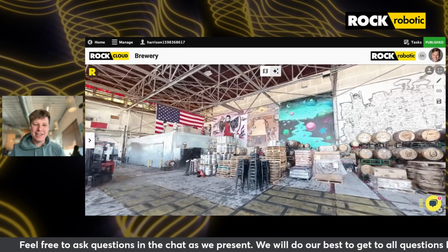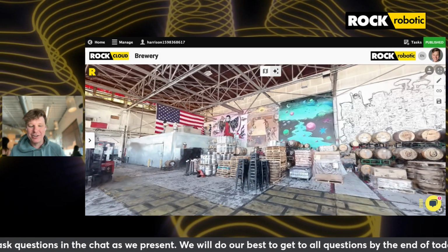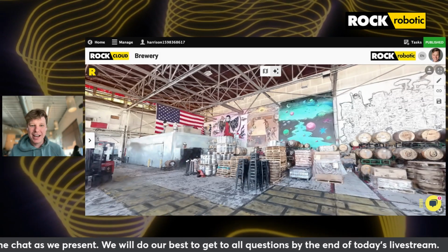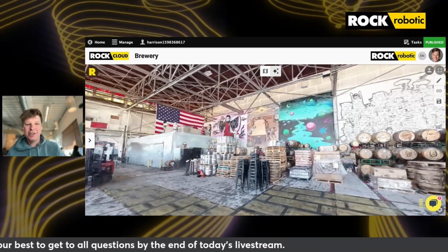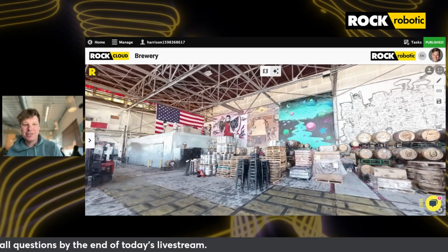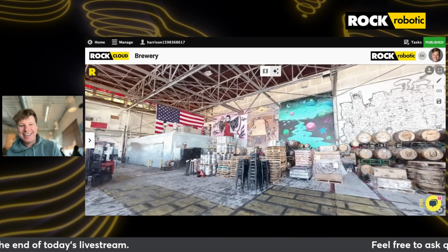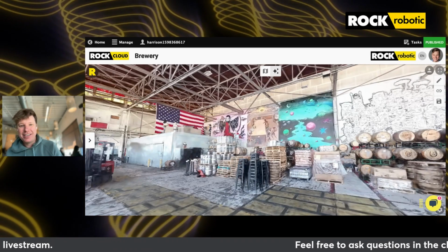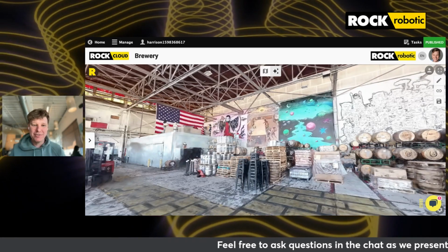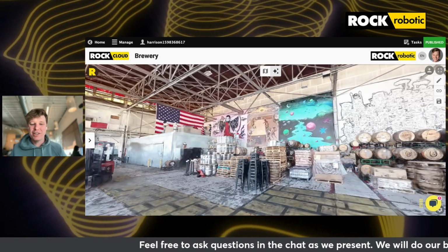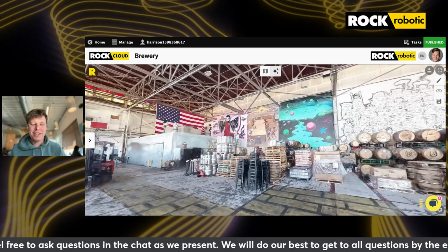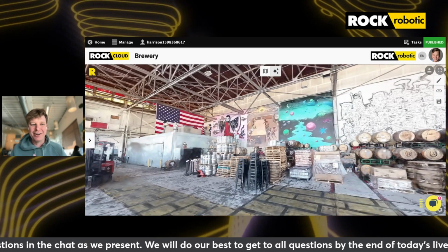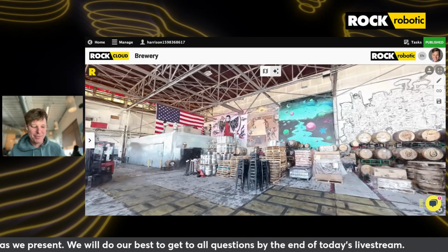And you're going to get that highly accurate, about 2 centimeters accurate at a recommended AGL flying height of those 3D point clouds. You can pull curbs off of it. You can engage with our Rock Pro services team to turn that 3D point cloud into a CAD model and then bring that right into Trimble Business Center or Virtual Surveyor or Civil 3D and work on the deliverables that we provide to you to finish your Alta surveys or et cetera, topographic surveys, whatever you're doing.